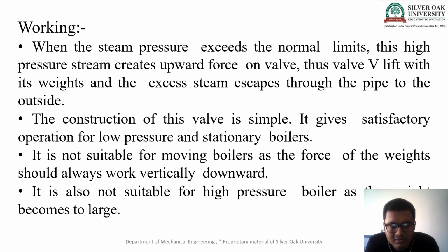So it is not suitable for a moving boiler, as the force of the weight should always work vertically downward. It is also not suitable for a high pressure boiler because the valve construction becomes large. If we have a high pressure, say 150 or 160 bar, then we have to put that much dead weight on both sides. So the construction and working get a little bulky.